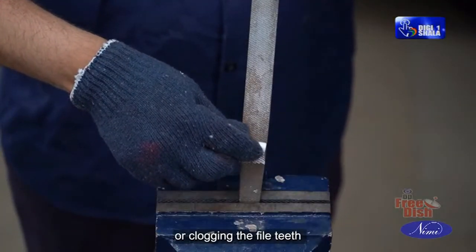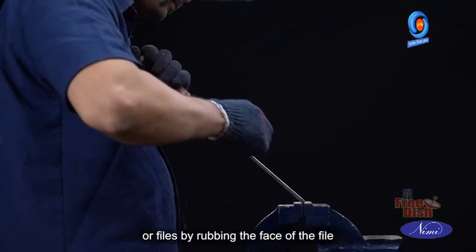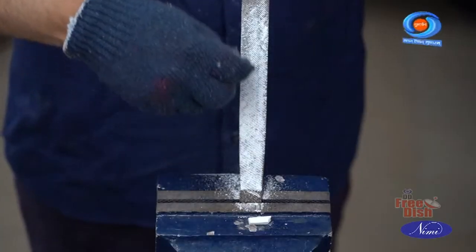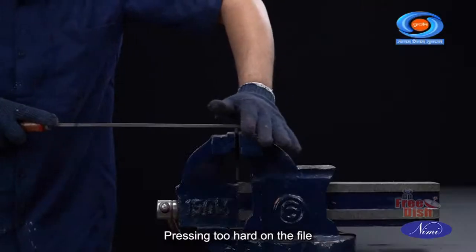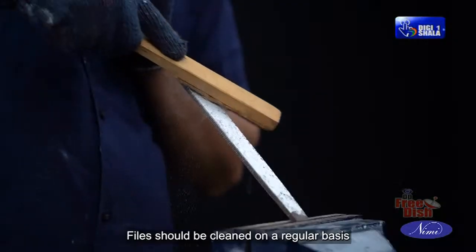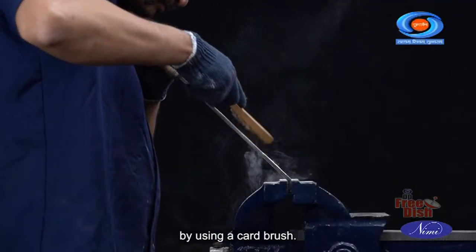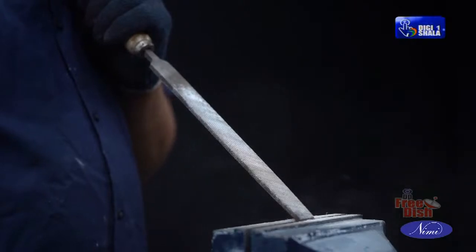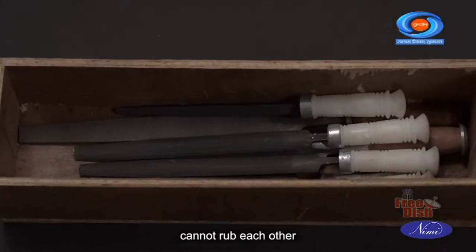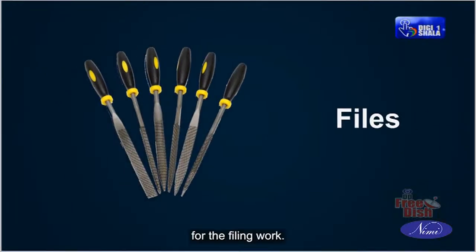Prevent pinning or clogging the file teeth with debris or filings by rubbing the face of the file with chalk before starting the operation. Pressing too hard on the file also causes pinning. Files should be cleaned on a regular basis by using a card brush. Files should be stored so that their faces cannot rub each other. Select suitable files for the filing work.